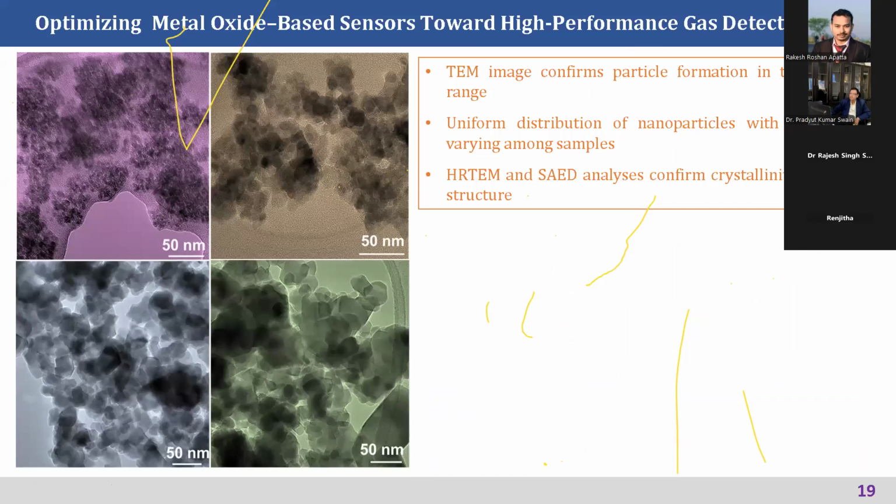Further, the structural morphology we analyze using microscopy techniques. We use electron microscopy: scanning electron microscopy and transmission electron microscopy. You must be familiar with the basics. Electron microscopy is a technique where you use radiation having a wavelength close to the features of interest in the sample. In these cases we are interested in atomic level features, going to nanometer features. For that reason, one has to use the electron microscope, so the electron is used as the radiation here.